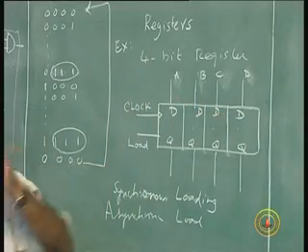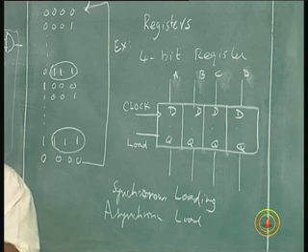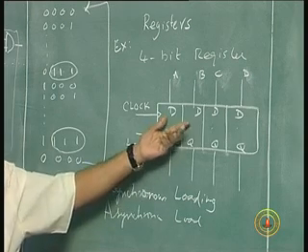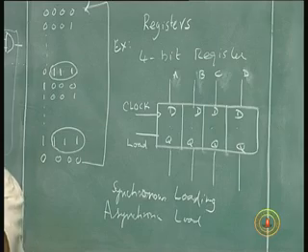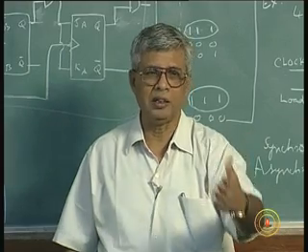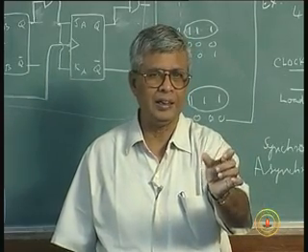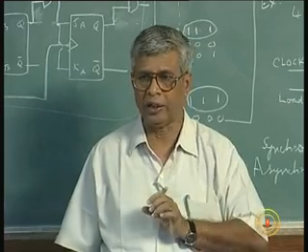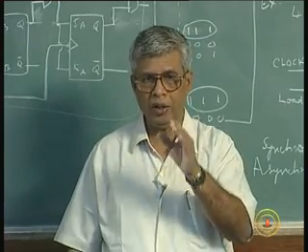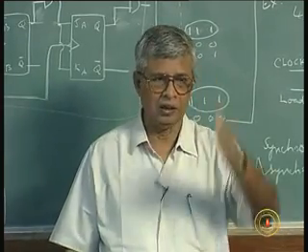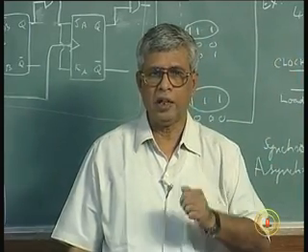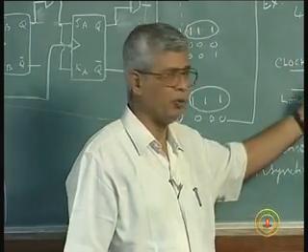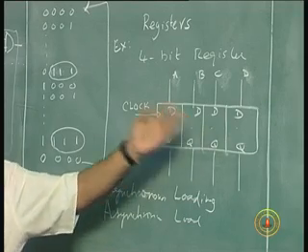Even when the clock comes at a very fast rate, much faster than the rate at which I want to read from this memory. Give an example, I have a clock of let us say 1 megahertz, that is the clock period is 1 microsecond. So, every microsecond we have an edge of the clock, whereas I want to put the data here and keep it for 100 microseconds.